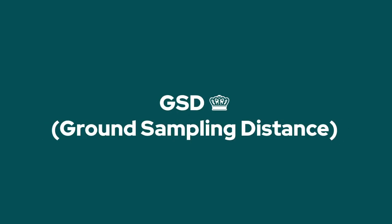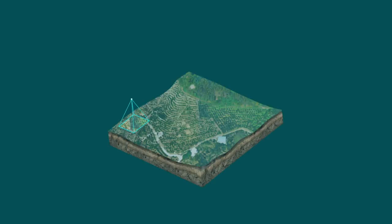This is why the GSD, or the ground sampling distance, really matters, and I really want to hammer home this point in this video. Essentially, getting close to the subject is what allows you to get detail in your data sets and allows those 2 points, whether they're 2D points or 3D points, to be captured in such a resolution that you can actually measure them to their true distance.